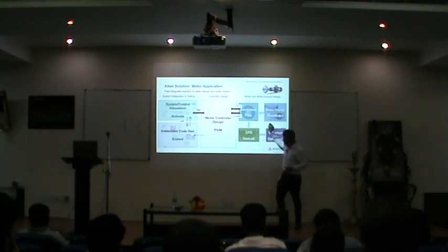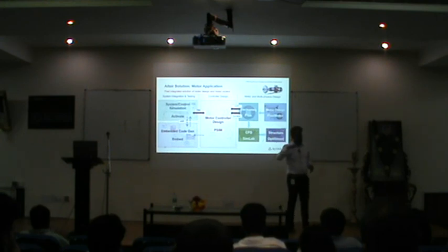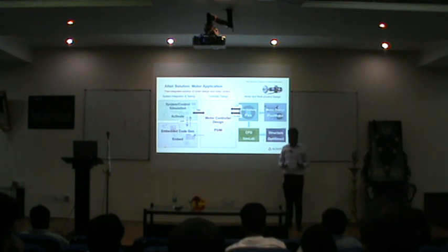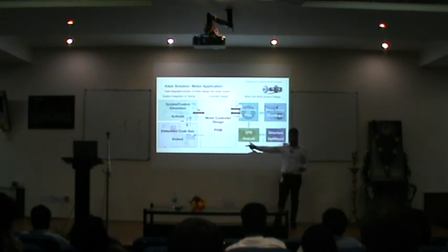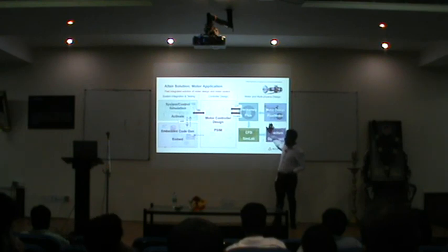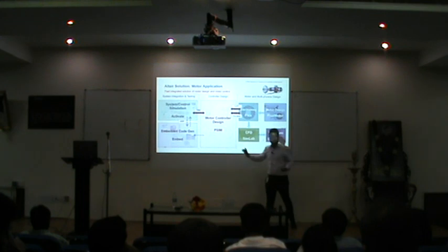Once you design the motors, bring that motor to PSIM and design the controllers, like doing speed feedback or other feedback. For any EV application, you want to control speed and torque. In that case, advanced control techniques like sensor or sensorless algorithms can be simulated. And then you go to embedded code generation and real-time implementation. So from a virtual design to the real-time implementation on the HIL, we have a complete workflow. You can do it. Okay.